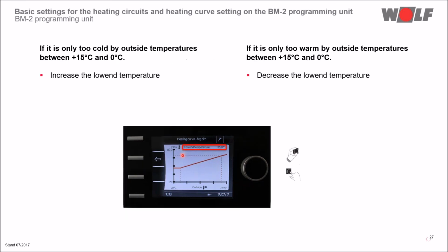If it's only too cold at outside temperatures between plus 15 degrees and 0 degrees, increase the low end temperature. If it's only too warm at outside temperatures between plus 15 and 0 degrees, decrease the low end temperature.